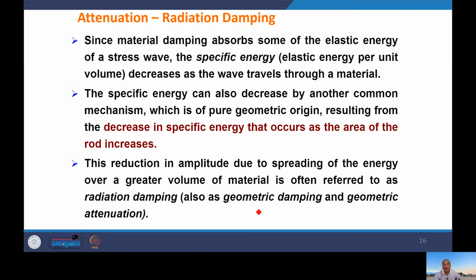And that is very important, because in case of structures, you have mostly material damping only, you don't have the radiation damping. But in the soil, if you neglect the radiation damping, then the results could be very much erroneous. So let's consider what radiation damping is.